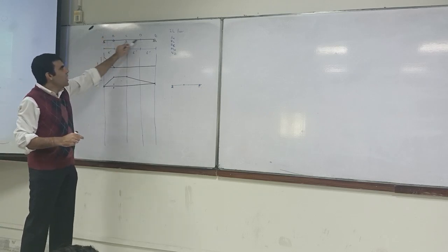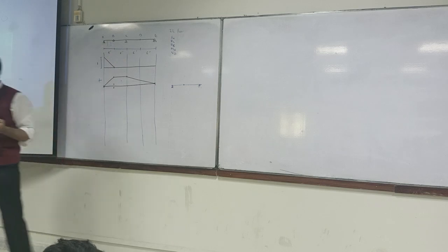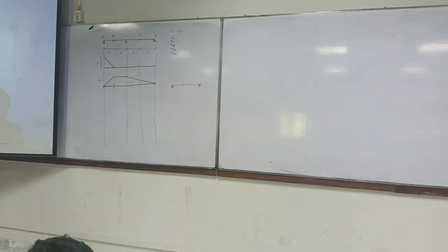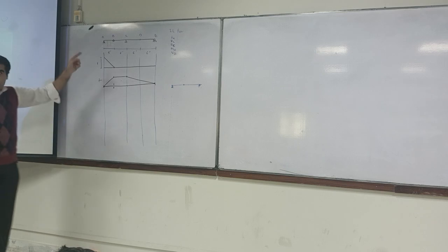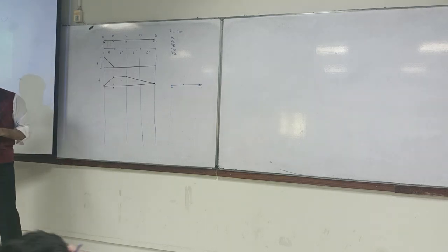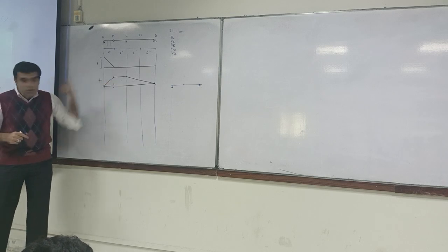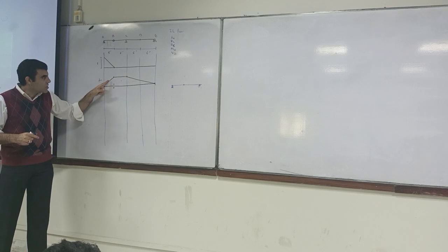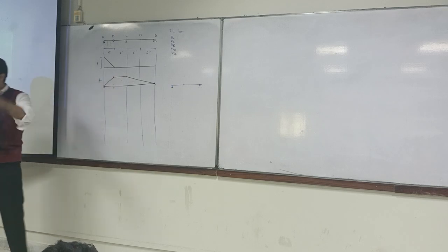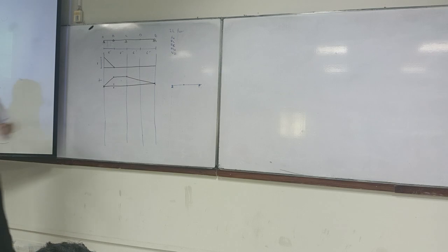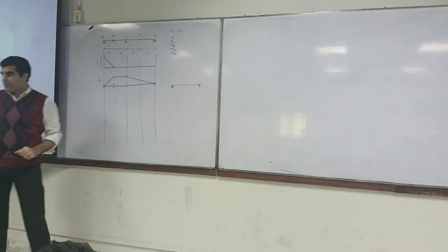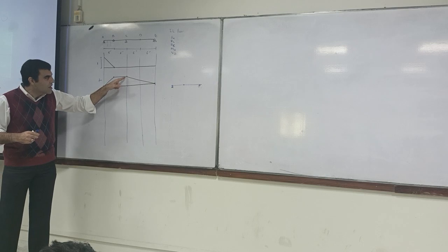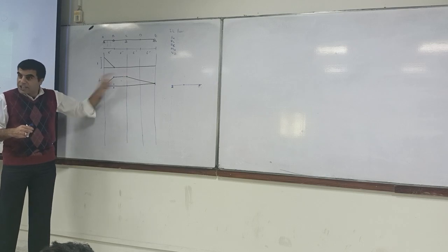In this member, how many links are there? What do we mean by links? Links are like a chain. In survey, you have done the chainage. That chain is made up of lots of links, isn't it? In this member, how many links are there? There is one link. So how can you introduce another link? According to this, there are two links. So these 1, 2 and 3 members are actually acting like a link. In the given question, you have got 2 links. So how can you have an internal hinge introduced over here?